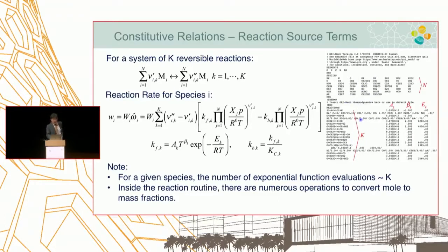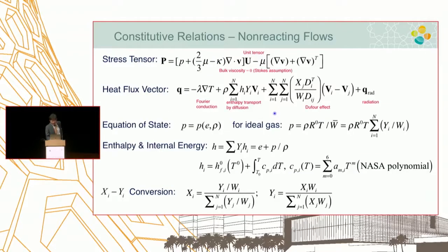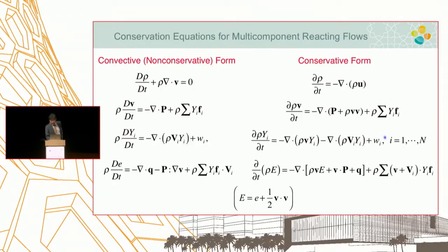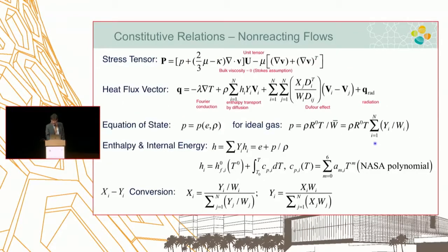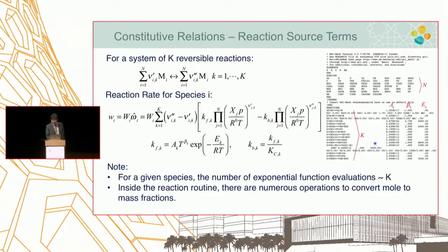And each of them is curve fitted by Arrhenius kinetic rate constants, and those are all computed in your code. And that goes back into the reaction source term. Every time you march over time by one step, this term must be computed by that formula. It costs a lot of time, but that's what is easily done these days. Computers are so fast, and you can do it rather easily.